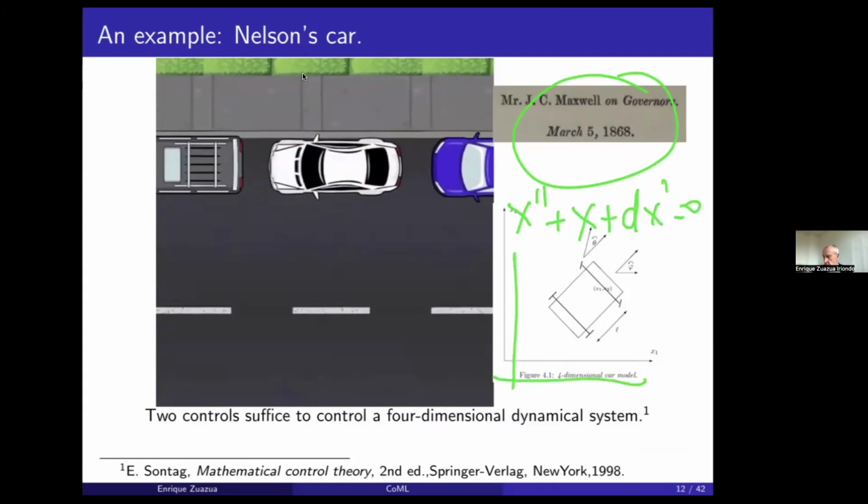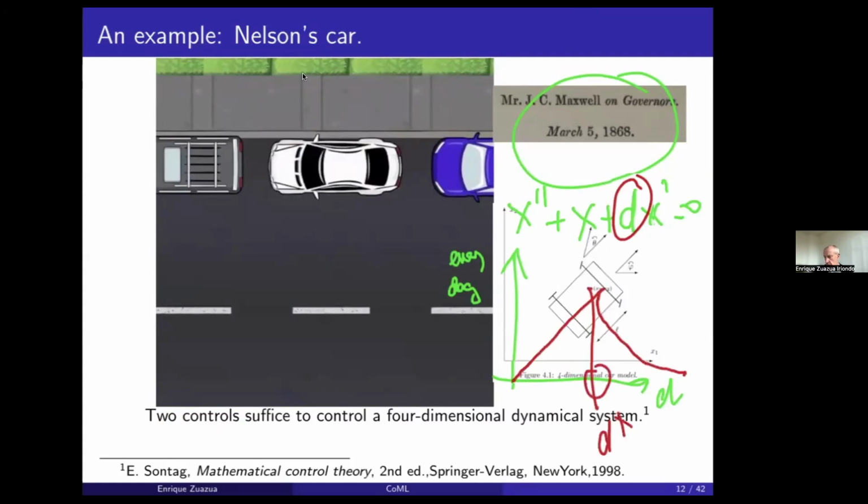And the key observation was that if you put here the amount of damping and here the energy decay, the path that determines how fast the energy decays depending on the size of the damping, in a rather anti-intuitive manner, this decay rate is not monotonic. Actually there is a threshold after which you experience the phenomenon of overdamping. Overdamping is like an overdose, that you can experience even with coffee, right?